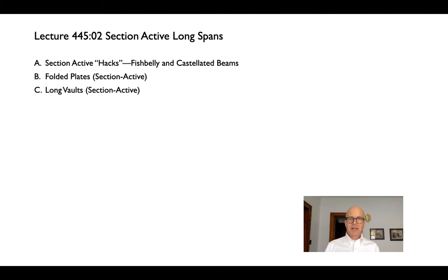This first little bit, we'll talk about what I think of as hacks, where we take standard beams and do things to them that make them much more efficient and therefore able to span farther. We'll talk in particular about a kind of beam originally called a fish belly beam, but what we can also think of as a moment-sensitive beam, in other words, looking at shaping the beam in the longitudinal direction.